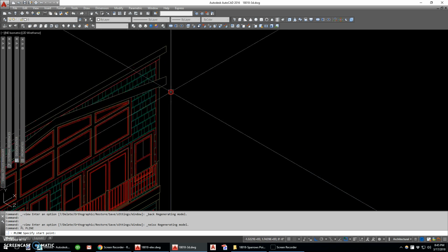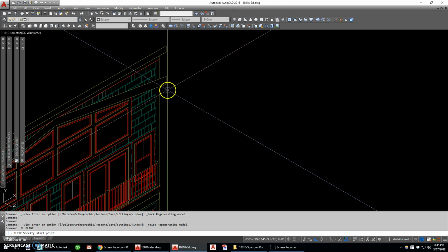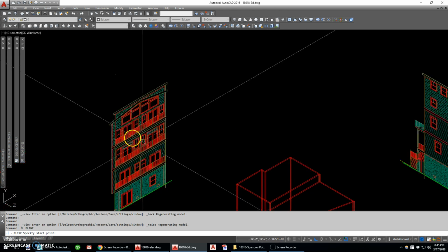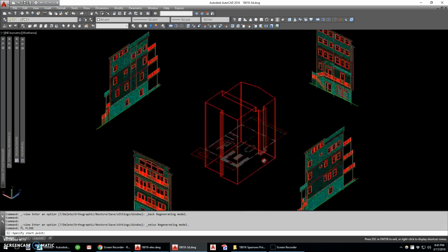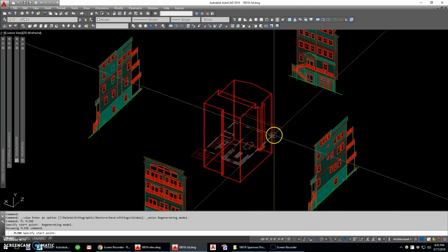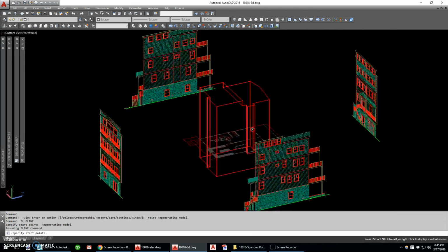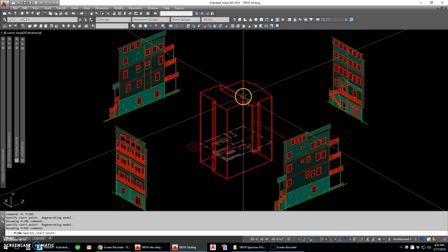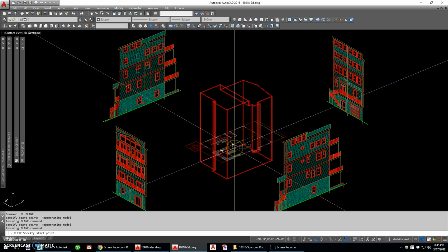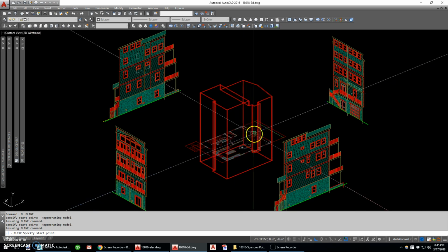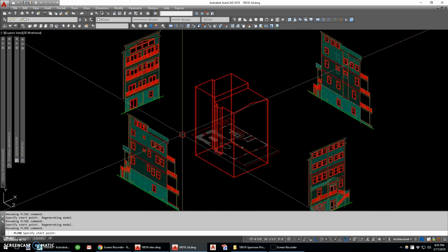Again, sometimes you won't see a roof on the back, but I'll draw all the general roof shapes and bump outs of the house, even if I don't draw some detail on the back. If this rendering is going to be from the front, I'm not going to draw all the window openings in the back, but I will put the roof on. What I don't want is the sunlight streaming through the house coming out the front windows. So a closed box for the rendering is what I'm looking for.